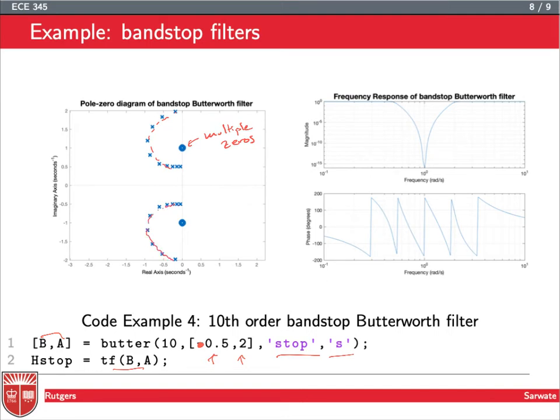But this is going to cause the band stop filter. The band stop filter kind of looks a bit like a notch filter, but you can think of all of these gains as being pretty small. So the 10 to the -5, 10 to the -10. So it's basically stopping all the frequencies outside this range where it's passing them. Low frequencies get passed, high frequencies get passed, but this little range here, which is a modest range between 0.5 and 2, this is getting rejected by the band stop filter. And again, we have all of these not real discontinuities in the phase.